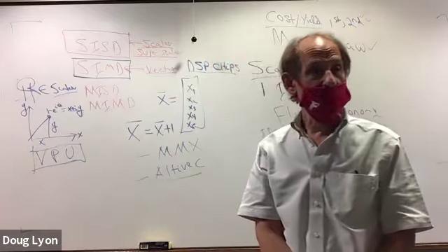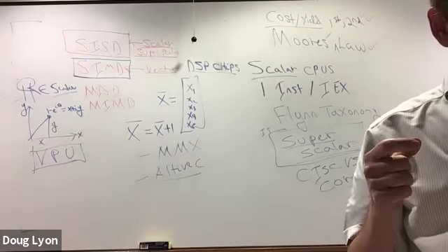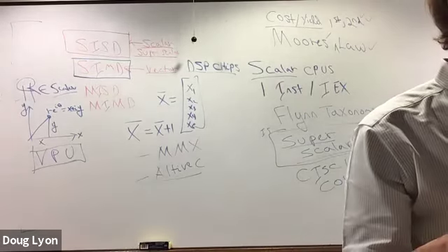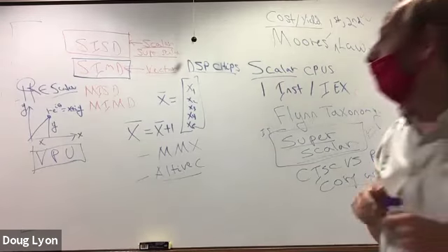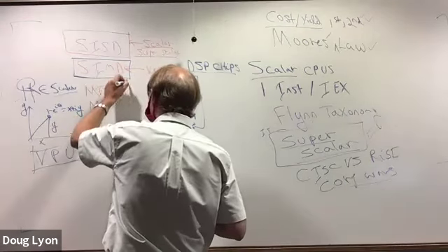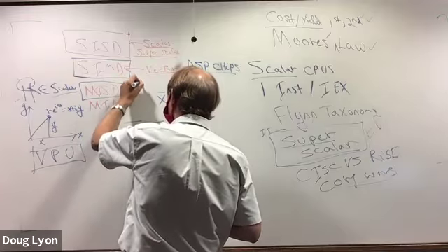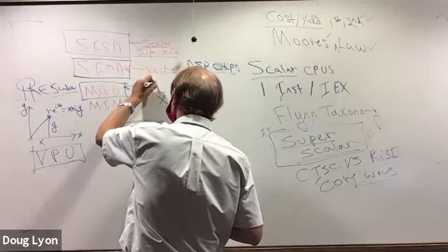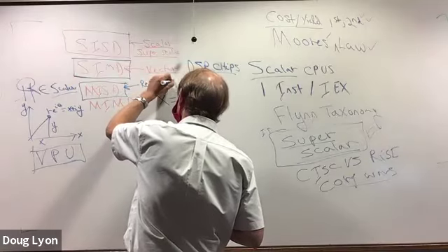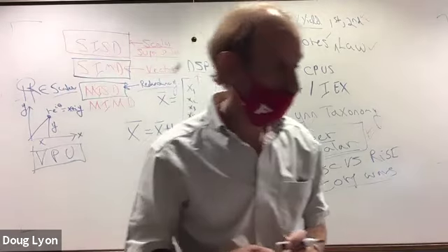If you had multiple CPUs operating on the same data, they could work in parallel and check each other. So this might be really good for the avionics of something that's mission critical. This is what you might call redundancy. And with redundancy, we can obtain reliability.